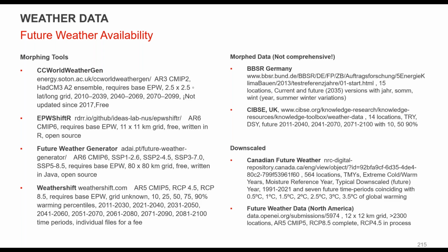Richard asked for the difference between mean coincident wet bulb and 99 or 99.6 design wet bulb. That's a great question. If you're looking at percentile, you'll have a 99% heating dry bulb, and then there'll be a mean coincident wet bulb associated.